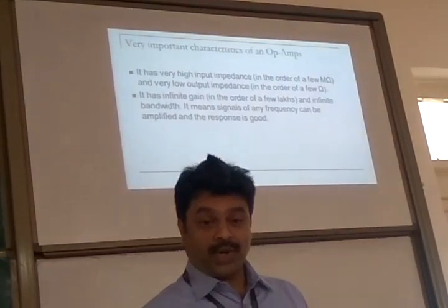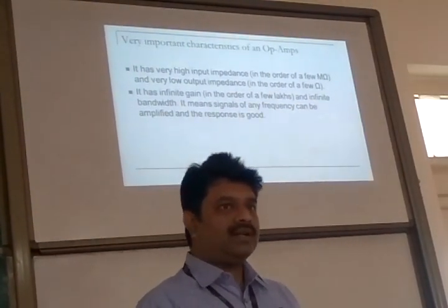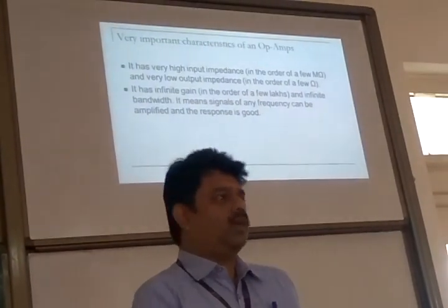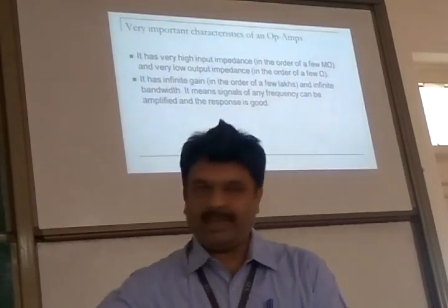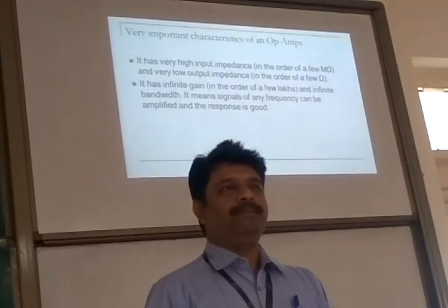You connect that to a circuit which has less input impedance, so it will draw current. The moment it draws current, there won't be any current for the thermocouple to provide and keep the circuit continuously working. It is something like that.